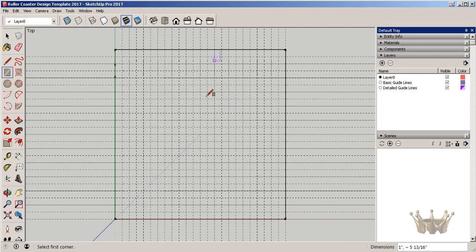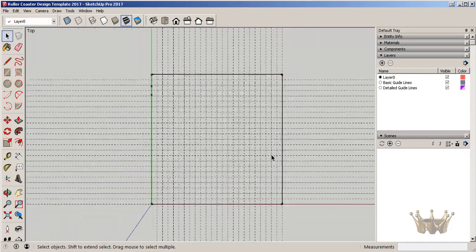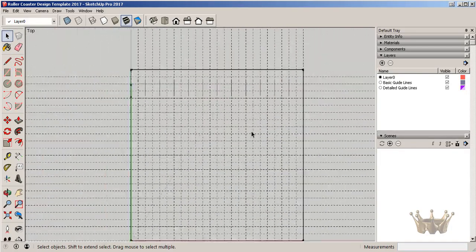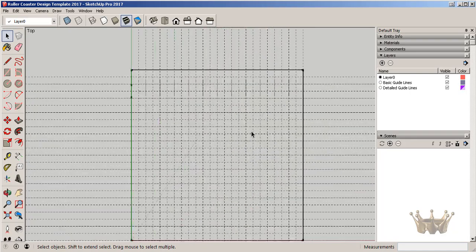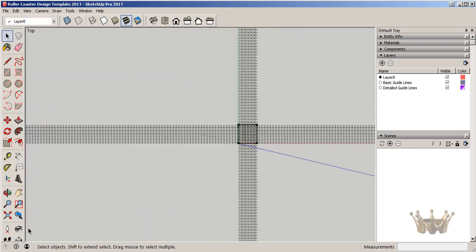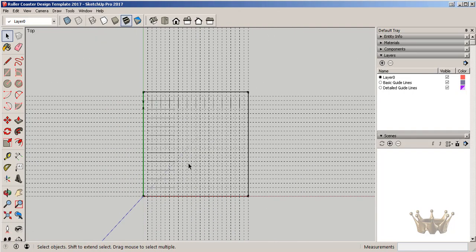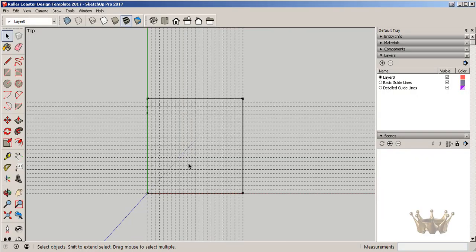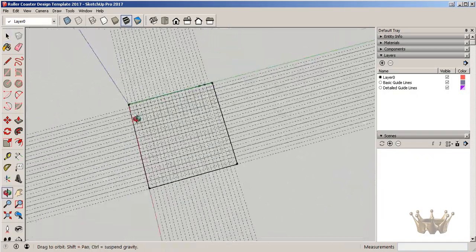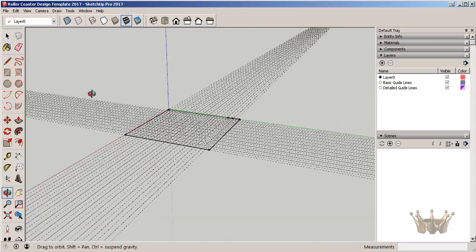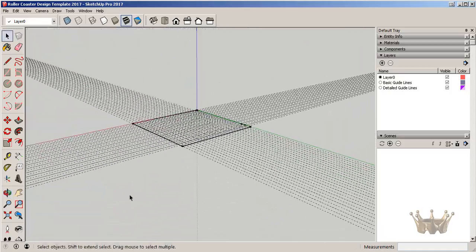You'll see that I'm directly over the top in this view, whereas if I press my mouse scroll button in and out, I'm scrolling in and out. If you scroll too far out, you can press the Zoom Extents tool to get back in close. If you press your orbit button, or the scroll wheel straight down, you get this. And we don't want this because this is a two-dimensional sketch and we really don't need to move around. We don't want to look top down.